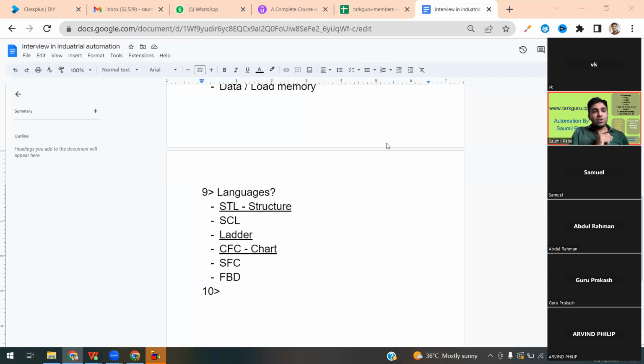There will be some function blocks to understand the cycle time. Cycle time, yes, definitely. For example, there is a cyclic interrupt, right? You need to explain it. Yes, this function block is available. If I want to do a particular task at an interval or at one particular time, there is a time-based interrupt. Or there are other different blocks, as I told you, the organization block, OB. There is not only one block, OB1.